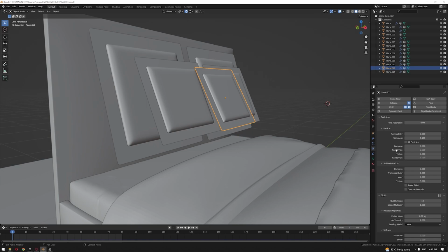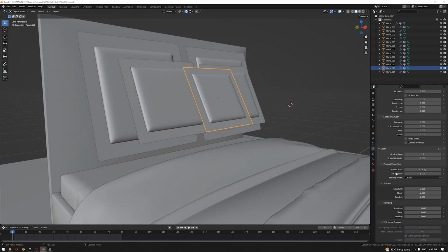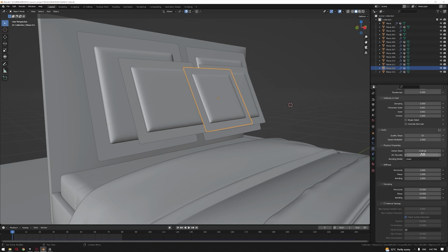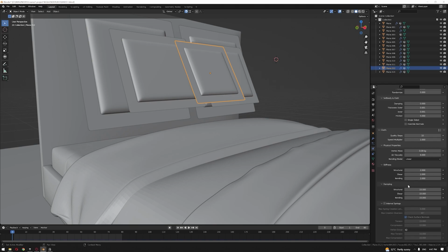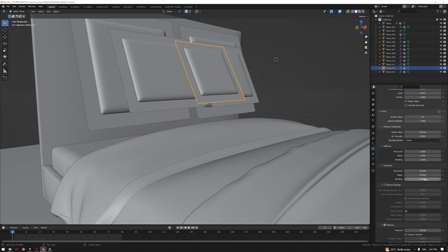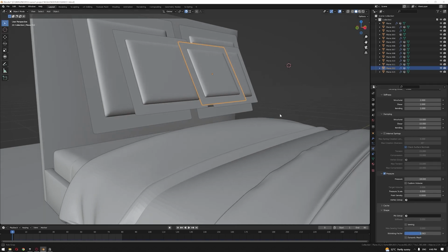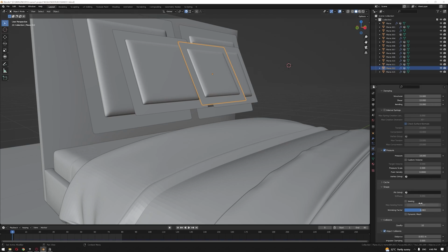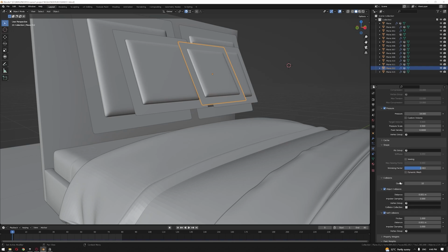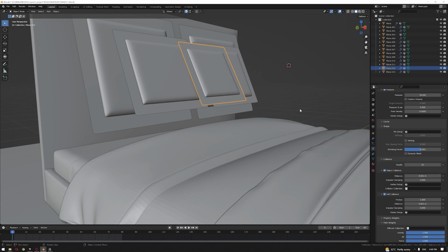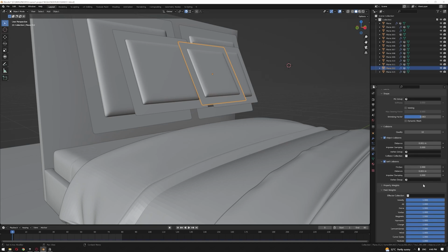Now for the cloth properties of them, they all are the same actually, just different sizes. So we put a very lightweight 0.09 and increased the air velocity, made the blending model to be linear, the stiffness and the damping. Just we played around with some values, and this is what gave us the best result. The pressure was 18 because we want the object to inflate along with a little bit of a shrinking factor, 0.063 on the negative side. No vertex rope, everything is simulated with collision on and a gravity.